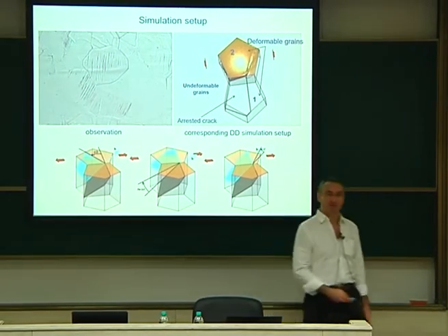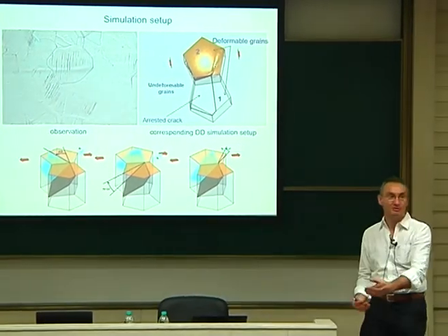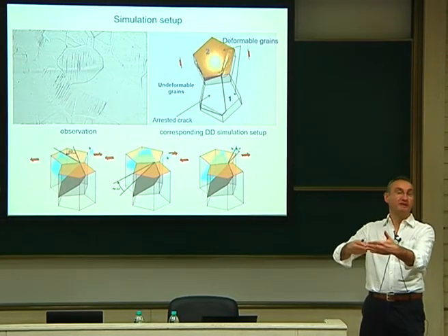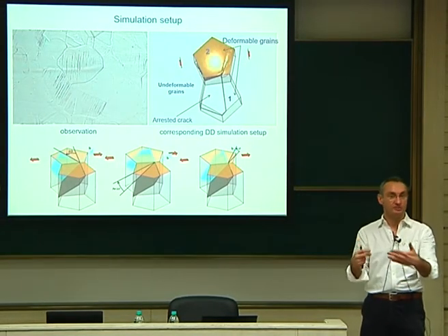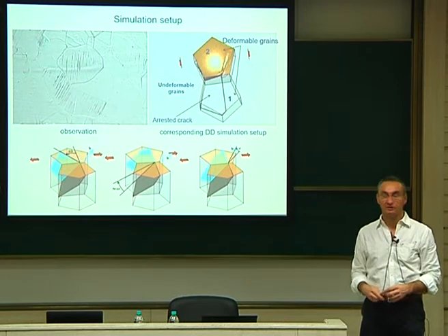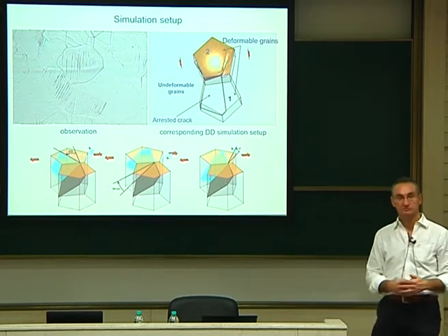You see, so you have your persistent slip band and your crack, and to define one compared to the next one, you should define three angles, Euler angles typically. So the tilt, the twist, and the theta angle. Okay, so those are the three that you get here.